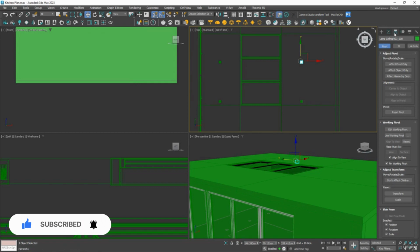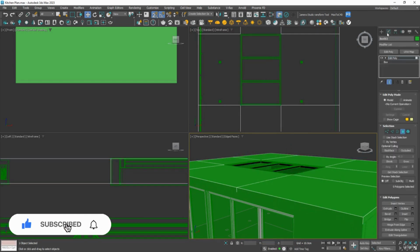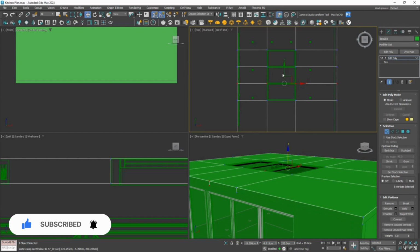And much like we did with the ceiling windows, we want a place for our lights to go. So selecting our ceiling, let's go back, and with Edit Poly selected, we can start connecting some of these edges. And I'm going to snap them to our lights.